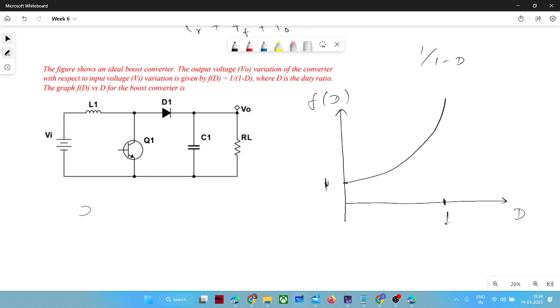This is the characteristic of the circuit, but it will not happen in a practical circuit because there you will have some finite resistances, and you will observe that some resistances will be added in the denominator. I am talking about inductor resistance and ESR, coil resistance, not diode resistance. So this is the characteristic of a practical circuit, not like this. You may find this in a textbook.